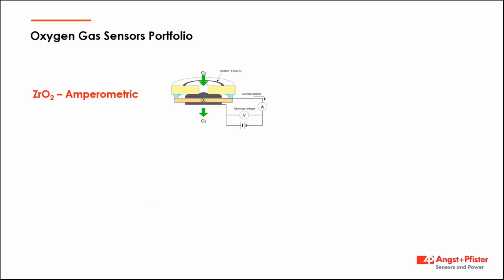An amperometric zirconia oxygen sensor operates on the principle of oxygen ion conductivity through a zirconium dioxide solid electrolyte layer. This works by a combination of a high potential field and a diffusion limited flow. The basic principle involves the measurement of the electrical current that flows through the zirconia electrolyte when a voltage is applied across it in the presence of gas containing oxygen.